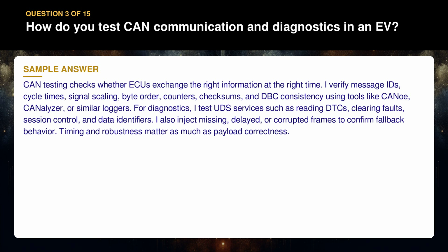or similar loggers. For diagnostics, I test UDS services such as reading DTCs, clearing faults, session control, and data identifiers. I also inject missing, delayed, or corrupted frames to confirm fallback behavior. Timing and robustness matter as much as payload correctness.